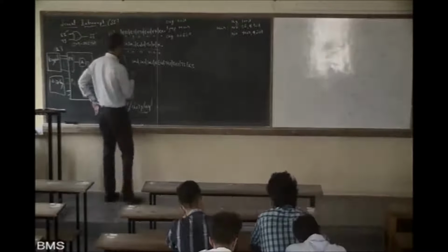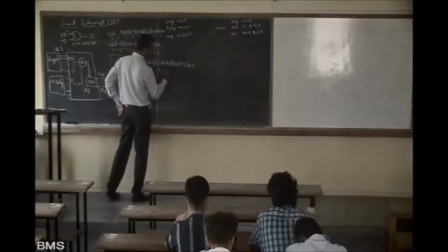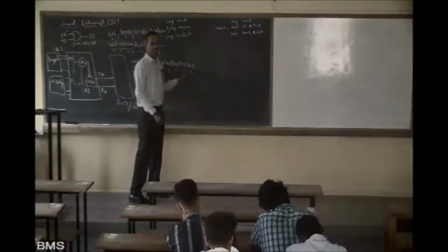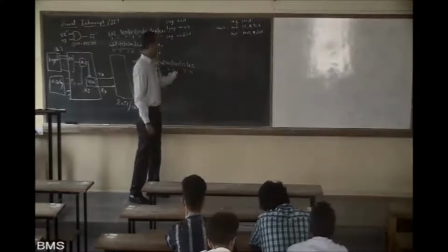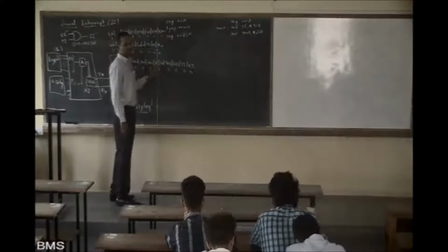50. Why 50? If I put 50, what happens? 0, 1, 0, 1, 0, 0, 0, 0. These two flags will rise when you are transmitting or receiving. Don't worry about this. RB8, TB8 are not used, so don't worry about them.